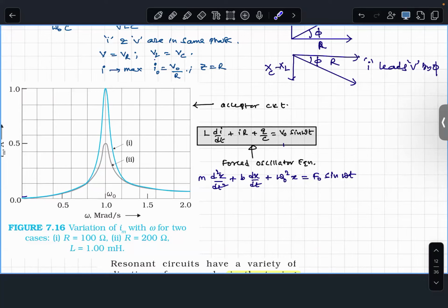Yes, obviously. XL is equal to XC, there is no reactance. Total power is waste. Cos phi is 1, which means there is no wattless current in this case. Everything is waste and converting to heat. Over a number of cycles, it gets converted into heat.